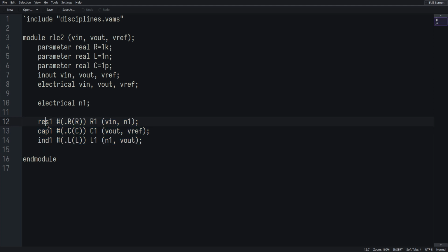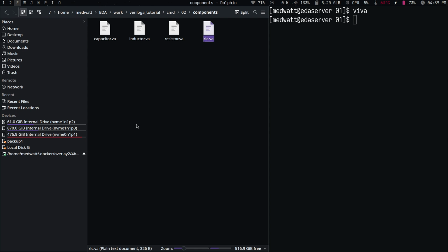And the Verilog-A language tells us exactly how we can instantiate modules. So basically, you give the name of the module, you pass in the parameters that you want to change based on the parameters that we get into this module itself. The instance, the label, we give the name in this module, and then we do the connections just the same way again.